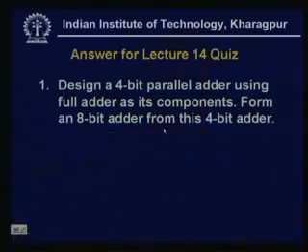When we drew the full adder, we used AND and OR as digital elements. Now the full adder is one module. First design a 4-bit parallel adder using full adders as components, then form an 8-bit adder from this 4-bit adder. Okay, thank you.